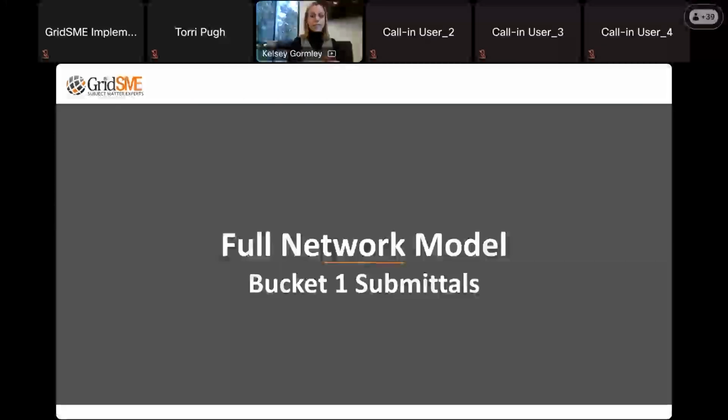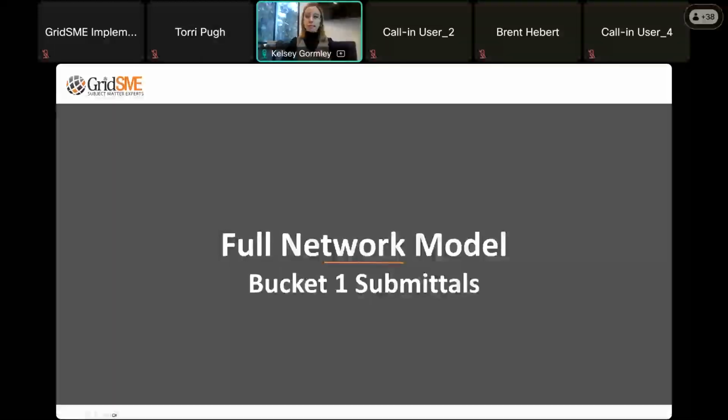All right, so we got oriented to how we create a project, and what different types of interconnection agreements are out there that allow us to create projects. Now we're going to start talking about actually submitting documents that represent your project characteristics to CAISO. This is really the first major milestone in the NRI process, which is the full network model. In order to be included in the CAISO full network model, we have to have all of our bucket 1 and bucket 2 documentation submitted and accepted by CAISO by their cutoff date. So go ahead and jump over to that.